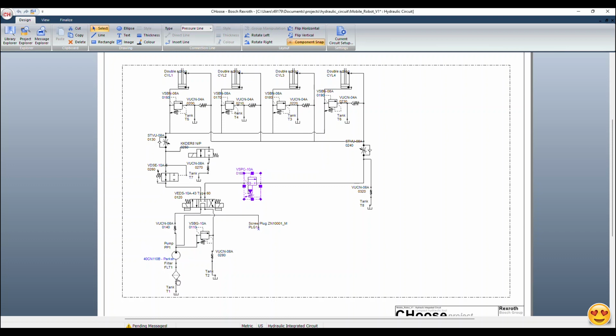And there's a tank which is filled with hydraulic oil, and it goes through a filter to remove non-intentional things or extra particles in the oil. And then after the filtering, it goes to the pump. So this is the negative side of the pump, and this is the positive side of the pump. And this side is the high pressure side.